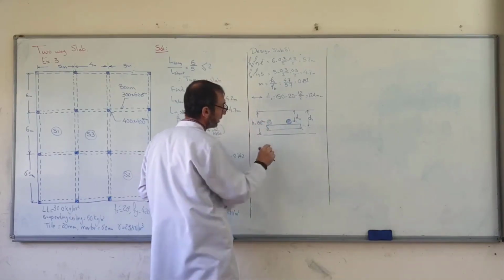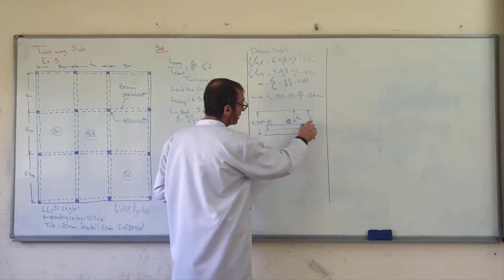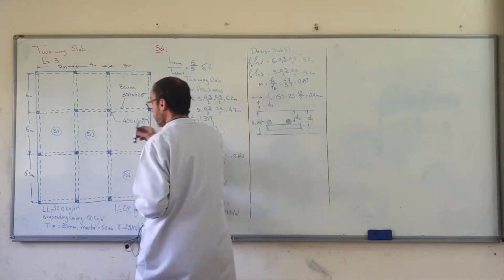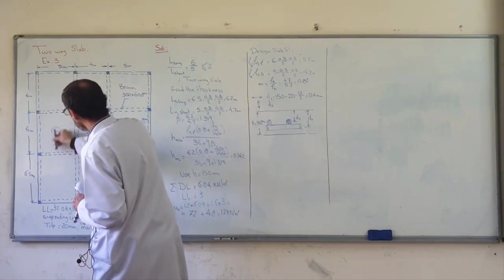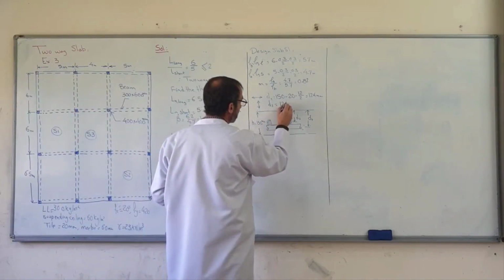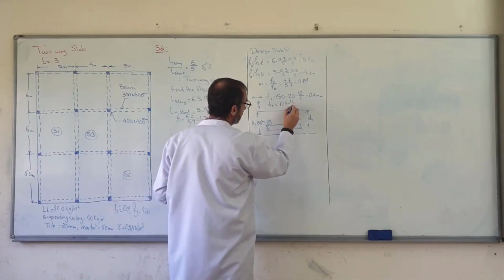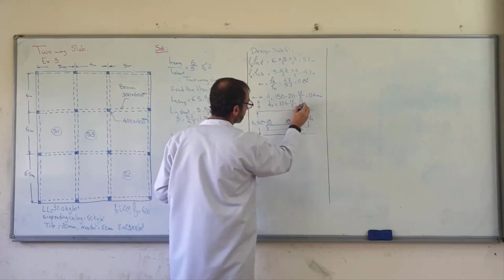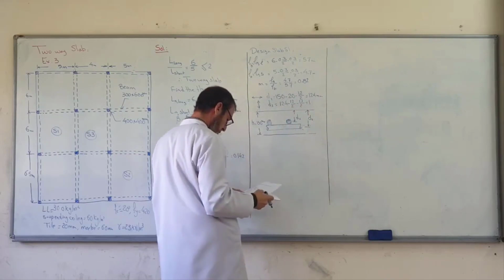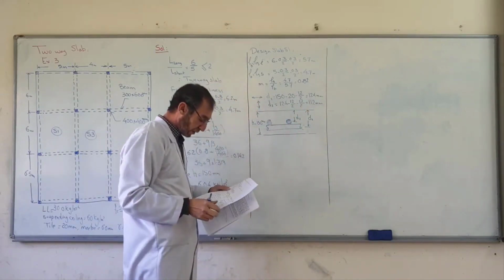Then this is the reinforcement. We take a section of the slab. This is D1 or this is D2. In the other direction, we put the reinforcement in this direction. In the longitudinal direction, D is equal to what? 150 minus 12 over 2 minus 12 over 2. This is 12, this is 12. It is equal to 112 millimeters.